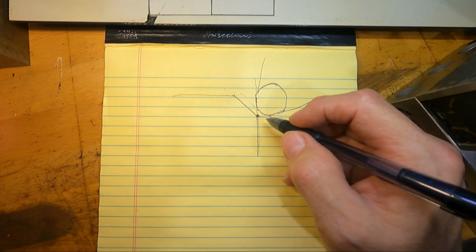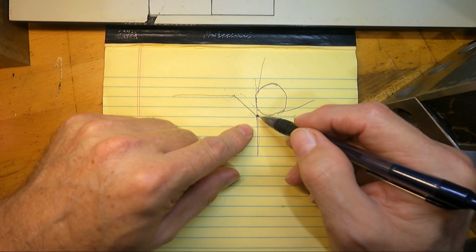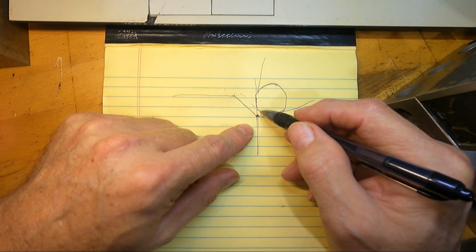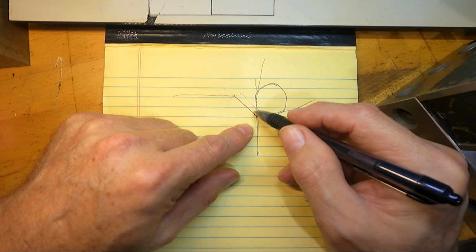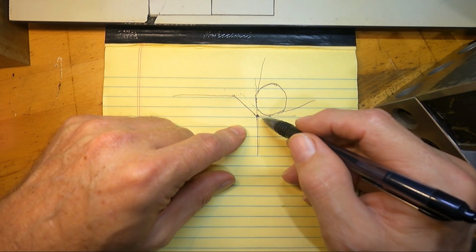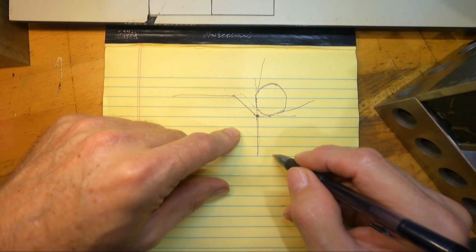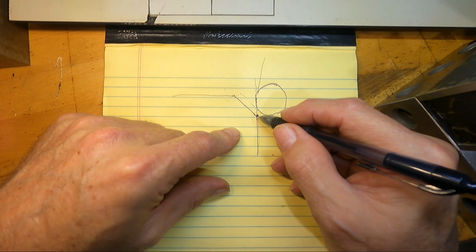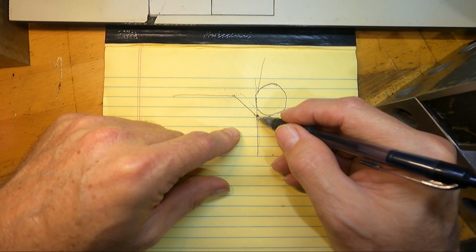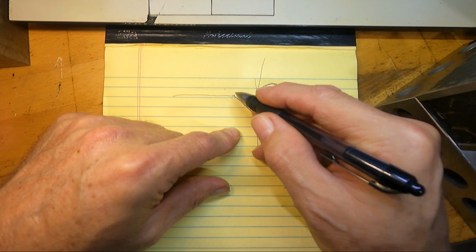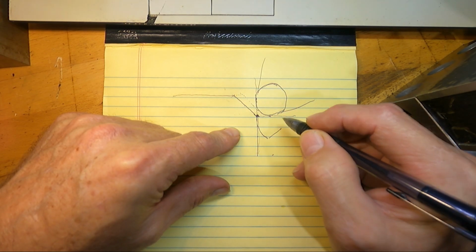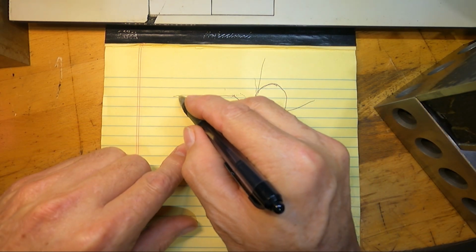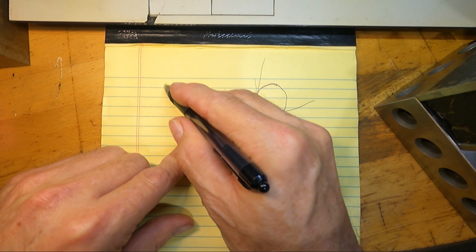So this is the reason you want to use a compensated tool path, is it would bring that radius of that insert down to this shape, whatever this shape is, if it's a radius or a chamfer or anything. And down here you'd have some kind of lead out movement. Generally for this kind of thing, I would put radiuses in these corners and lead in with an arc, and then go down my contour and lead out with an arc and out.